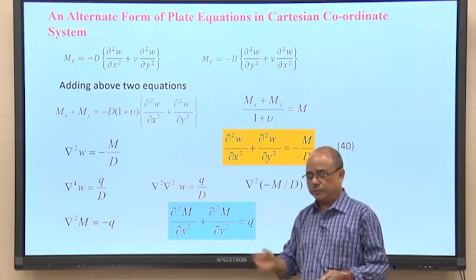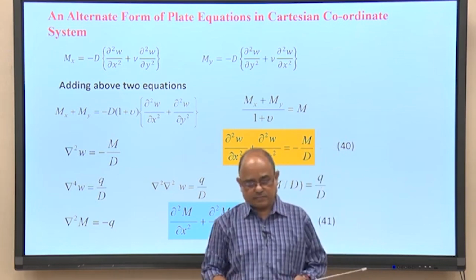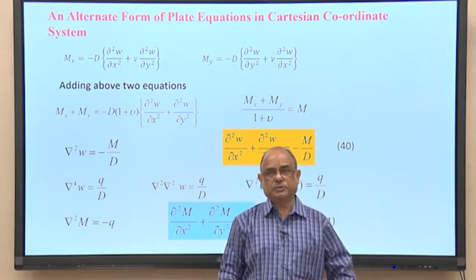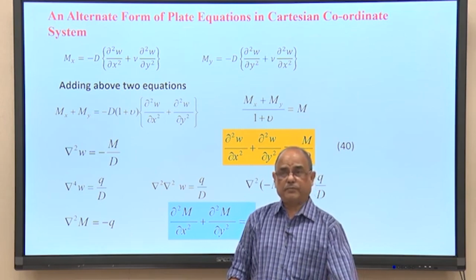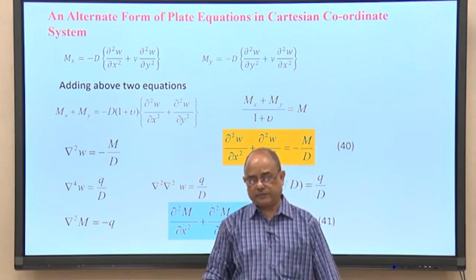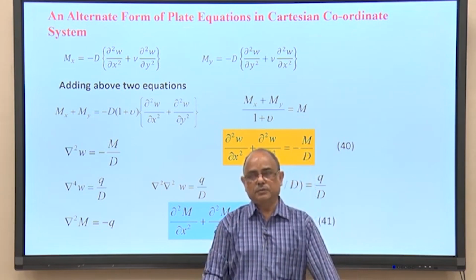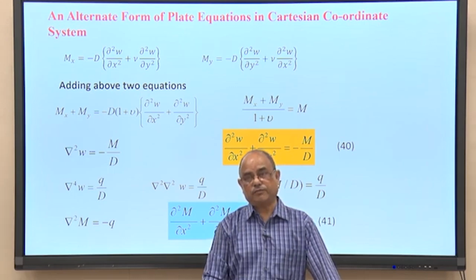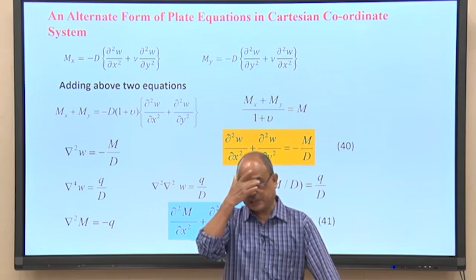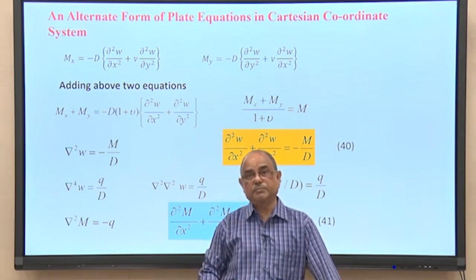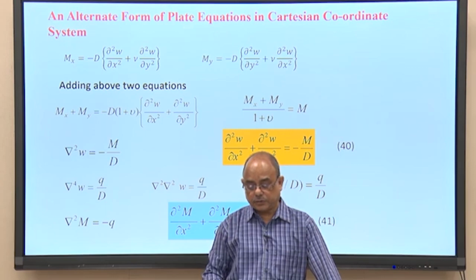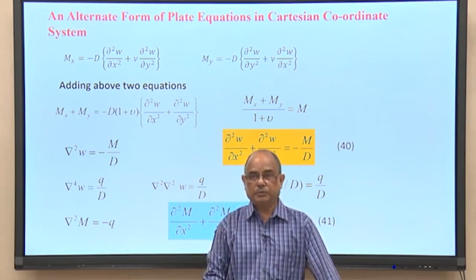Conveniently, the fourth order equation is used for plate problems, finding the deflection and thereafter the bending moment and shear force. We use the plate equation of fourth order. But if anybody is interested to interpret the results in analogy with the membrane equation, then the second order equation can also be used.